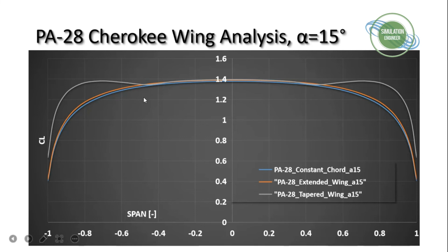So this also confirms the theory, because the lift-induced drag coefficient is produced because of these tip vortices and this complex phenomenon which is occurring over there. So this also reduces the strength of these vortices, and in turn reduces the induced drag.